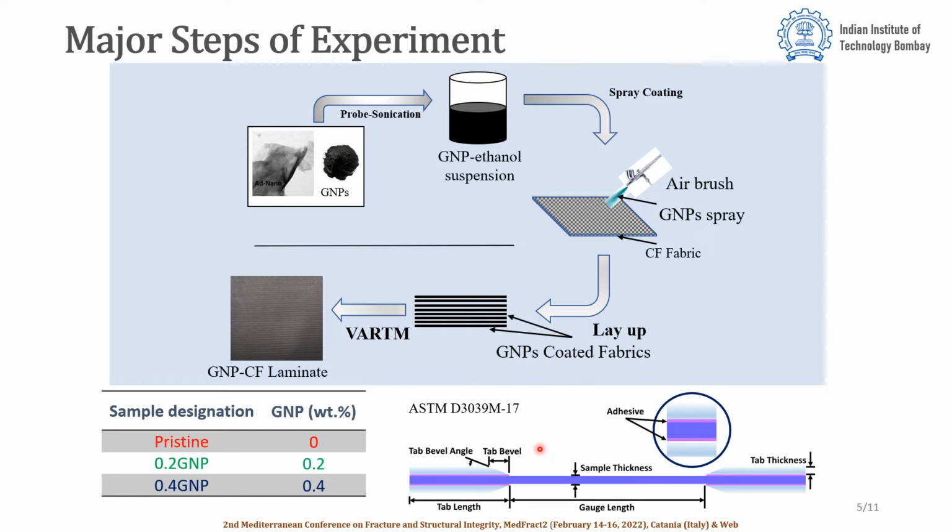After the laminate manufacturing, the static tensile test was carried out as per the ASTM standard, and the specimen is shown over here. The tabbing was done to the grip section of the specimen on both sides, and the specimen was 150 mm in total length, 25 mm in width, and 1.7 mm in thickness.